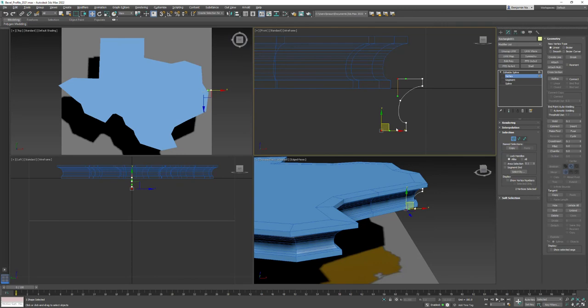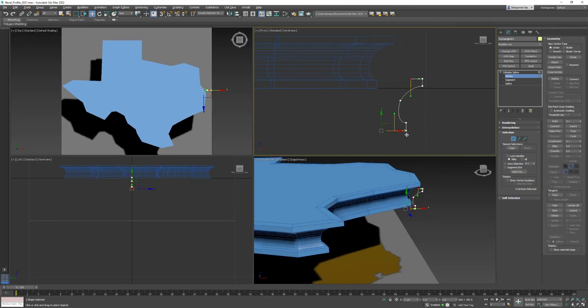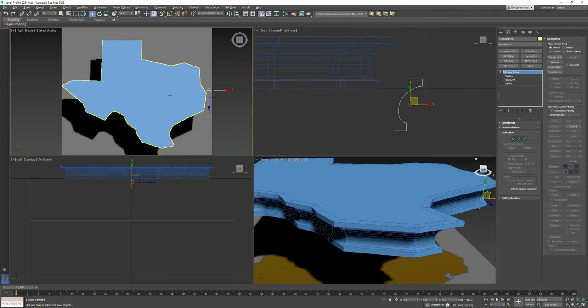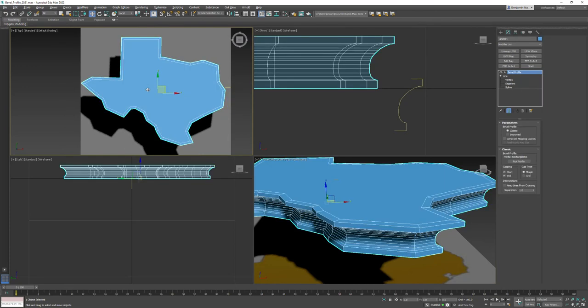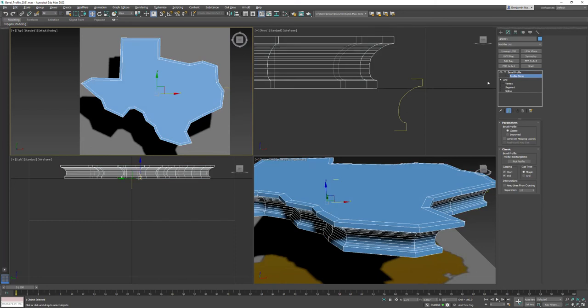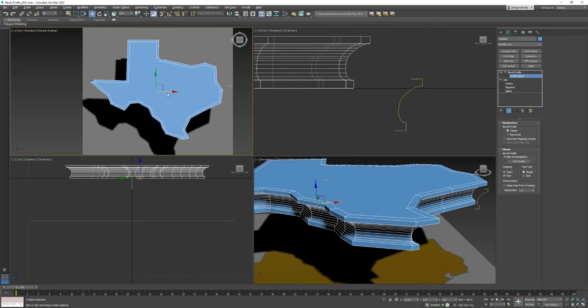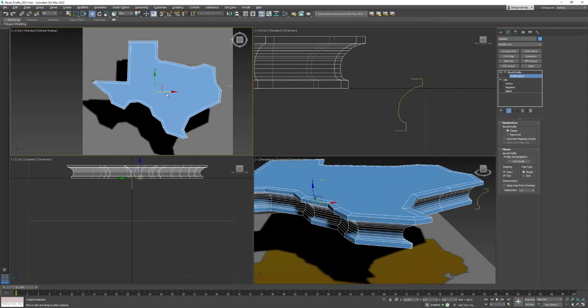We can actually grab those vertex points and move those over. Maybe we don't want them that long. Just right click on those specific points and make them corners. But see how now it's kind of matching that. Now, the overall shape is a little bit larger than we'd want it to be for the table. So maybe we'll come in here to Profile Gizmo and, knowing that it's a left-right movement because of how the model's made, we can push this in to get it to line up a little better. There we go. I can turn that off.